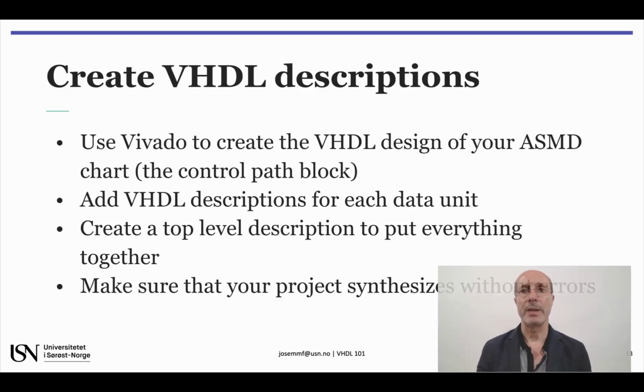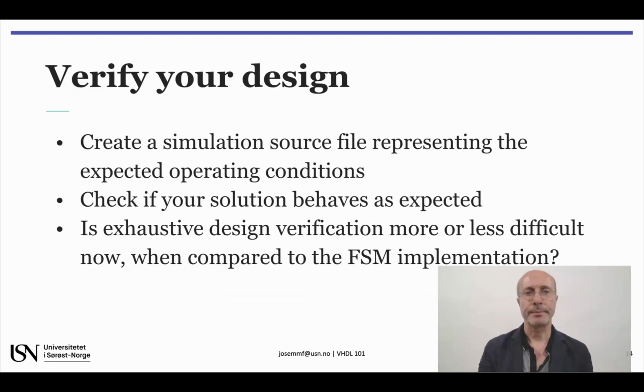In this case, it's once again better to consider a hierarchical structure description where the top level interconnects the control path and the data units. You will need to create the VHDL design files for each block, and then bring everything together and check that you are able to synthesize without errors.